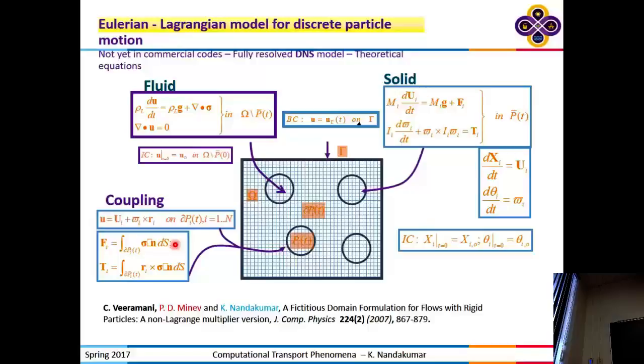Right? The fluid exerts forces and torques on the particle, which go into here, the force and the torque. And the particle motion, this u and omega, determines the boundary condition for the fluid. Okay? So when the particle moves, it pushes the fluid. When the fluid moves, it pushes the particles. So this is the most rigorous method for tracking multi-particle systems with complete two-way coupling, no approximations, and this is why it's called the direct numerical simulation of multi-phase flows. It's a very expensive calculation.